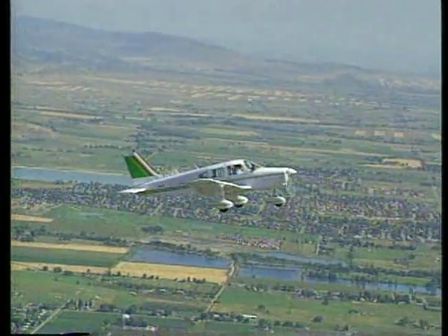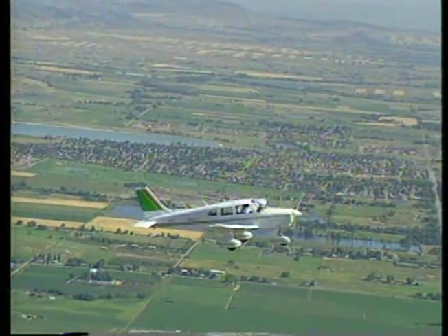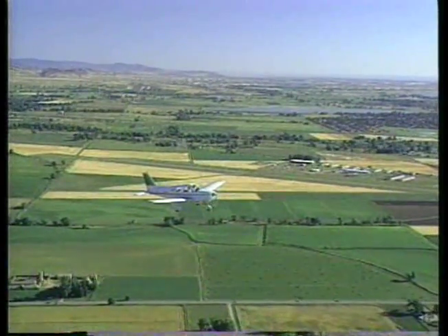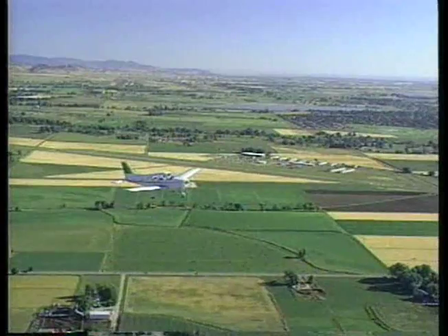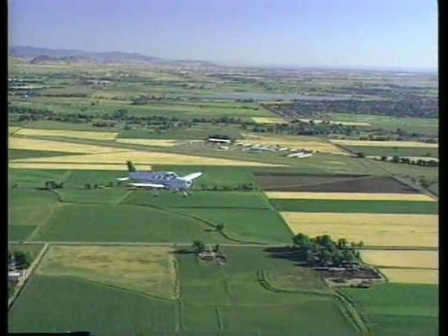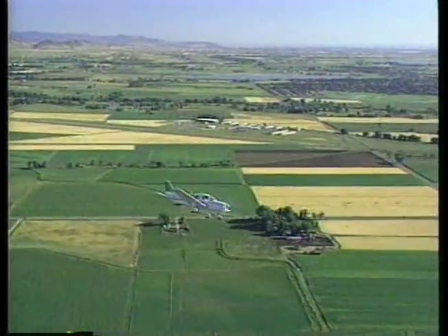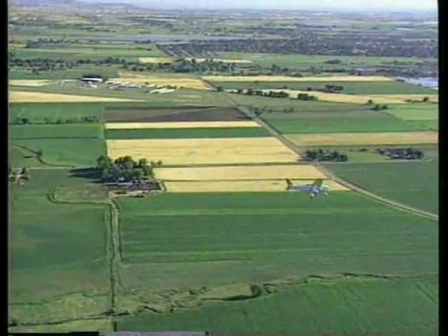Practicing stalls is not meant to increase your ability to stall an airplane, but to help you recognize the onset of a stall and how to prevent it. Or, if one does occur, what procedures to use to minimize the loss of altitude. In addition, by practicing a power-off stall, you'll get a better idea of what can happen during an approach to landing if your attention is diverted from flying the airplane.